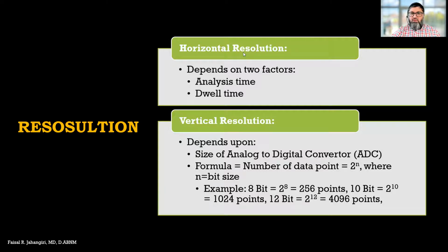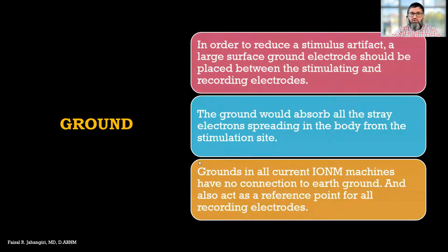So we talk about this one: the horizontal resolution depends on two factors, analysis time and dwell time. And the vertical resolution depends on the analog to digital converter size, so depending on how many bits you have, you will have that many data points on the top.